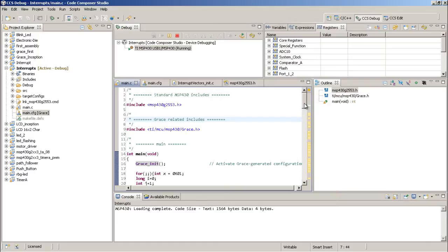In the ISR, interrupt subroutine, all the statements that are written are executed, and after the last instruction it encounters a return, and it returns to the main program by moving the contents of the stack onto the program counter. So that is related to the working of an interrupt.